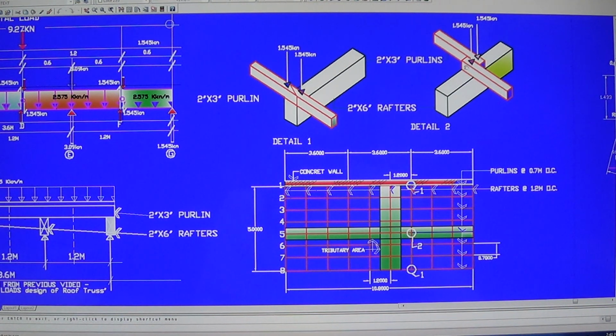At the midspan, the purlin is arranged like this, it's overlapping, like a jagged edge. And at the very end purlin right here, against the wall and the edge of the rafter, we're gonna install the gutter here for the rain downspout. So it has to be spliced like this in one line.